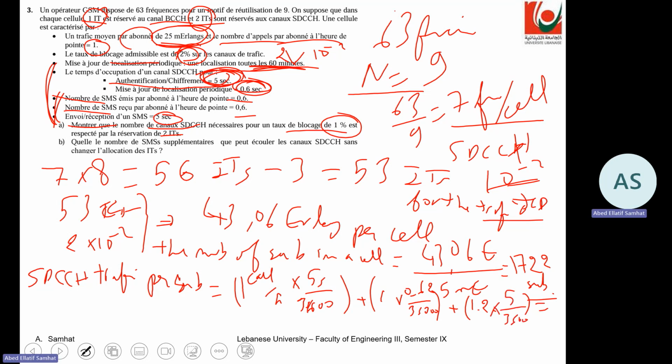Okay, so in this case, if we calculate those, we have the SDCCH traffic per user, and in this case, it's around 3.2 millierlang. So here we have the signaling traffic or the SDCCH traffic generated by one user in the cell.